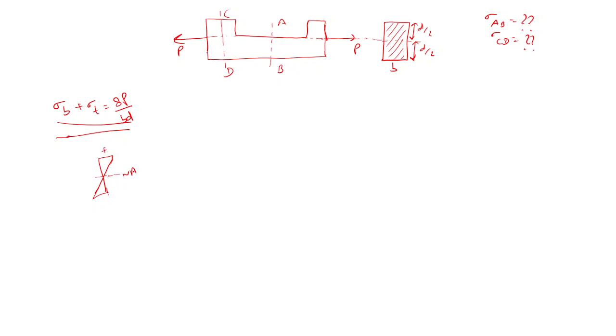So let's suppose here positive and here negative. Whatever would be there, here maximum positive and here the same value maximum negative, right? Getting this point or not? Yes, sir, this is a deformation, the distribution of bending stress on the cross section. Actually, since both are normal stresses, we are able to add them. Because tensile stress would anyhow be positive, the maximum would be on the upper side. If I solve this, then we will see how we can.